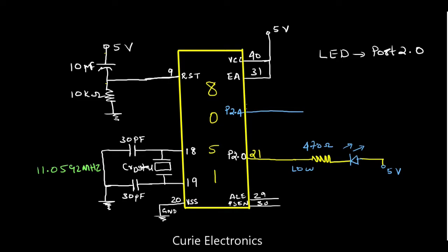After that, we have to connect the switch. I have used a push to on switch. When I press the push to on switch, the switch will make contact and this goes to ground.